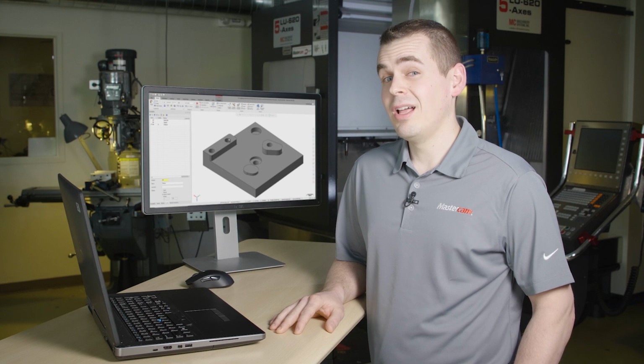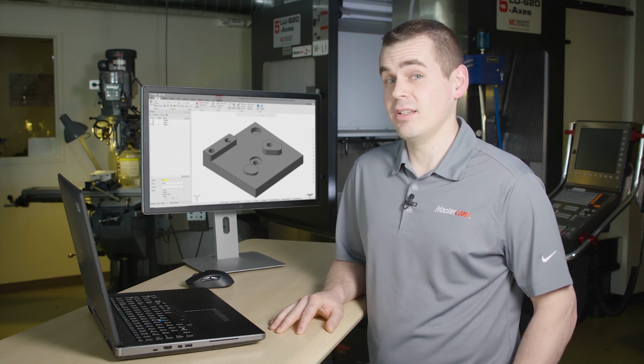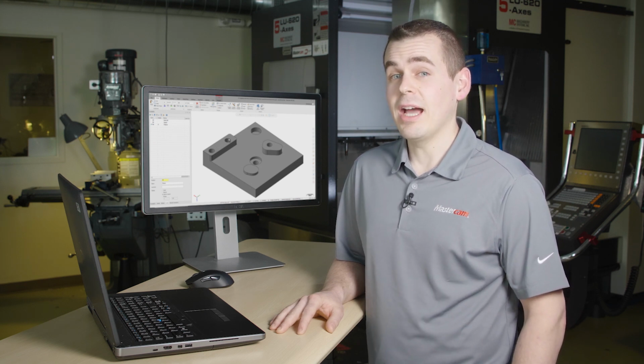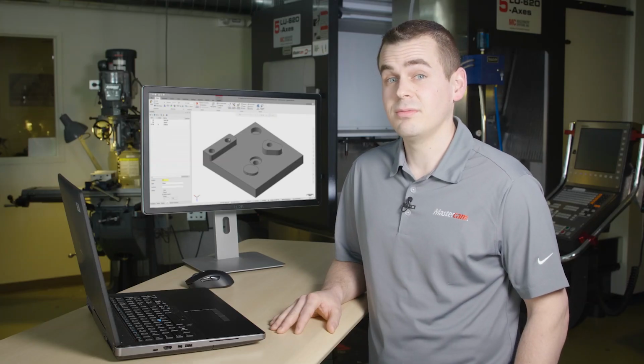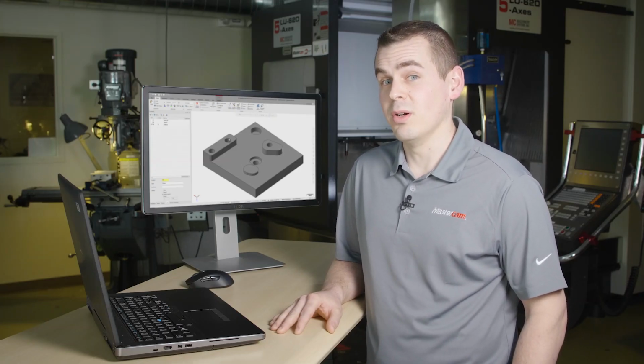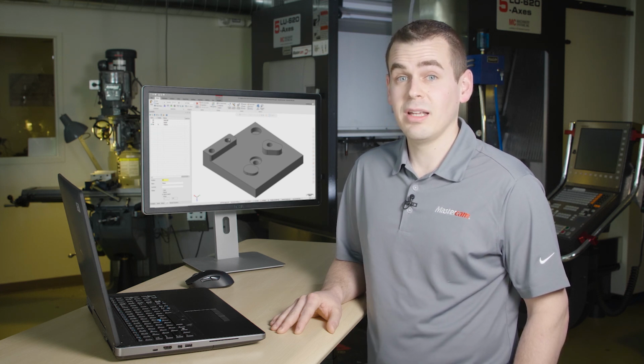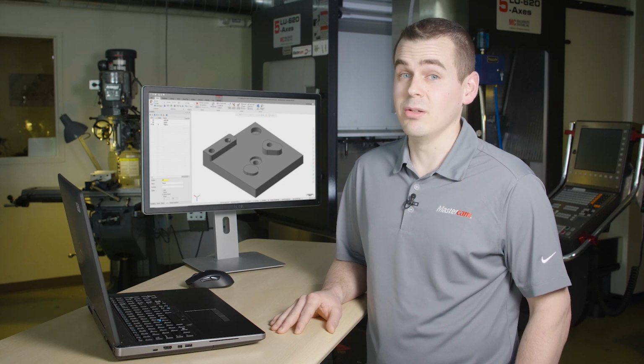For a drilled hole, I don't necessarily need to change the diameter of the hole in the solid. I could simply select the center point and use an appropriately sized drill. But if I need to use this model again in the future, or if someone else needs to machine this model, it's far too easy to mistakenly drill these holes incorrectly, since they are wrong in the model. It's a much safer workflow to correct the hole diameters now to avoid mistakes in the future, and Add History makes it easy to do.